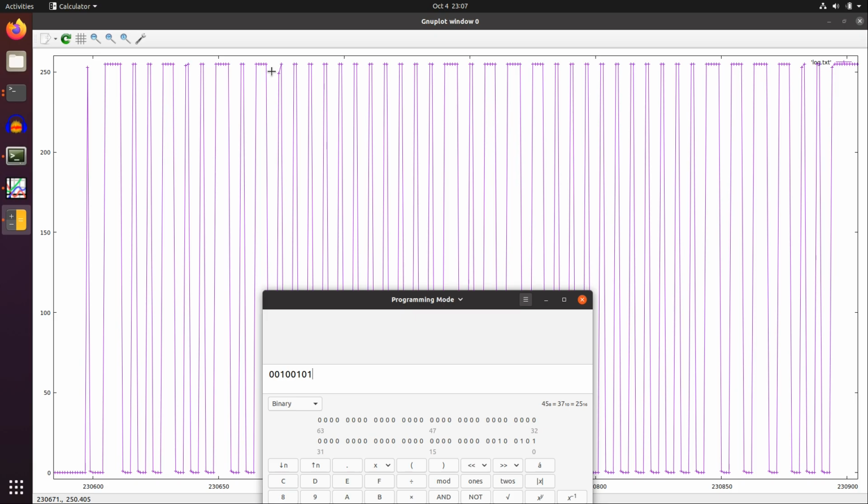Then follow a few zeros. So we have here 1, 2, 3, 4, 5, 6, 7, 8, 9, 10, 11 zeros. The first 8 after that, so from here to here, represent the decimal part of the humidity. The DHT11, however, does not have the resolution for a decimal part. So the maximum resolution for the DHT is 1. So it can distinguish, for instance, 37% and 38%, but not 37.5 or 37.8. That's why these bits are always 0.